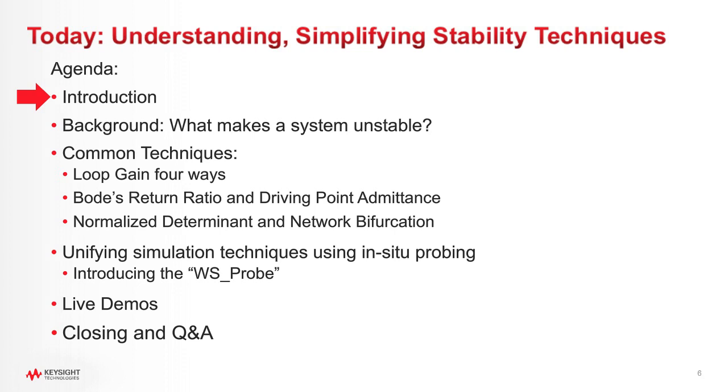The sweep points, yeah, if you don't have enough sweep points, you can certainly miss high Q oscillation. So I've seen that happen before, but it's not a problem with just K-factor. That can happen for anything. And it only applies to one stage of an amplifier. Actually, K-factor only applies to the external parts of an amplifier, so like the source and load terminations. All right, so there you go.